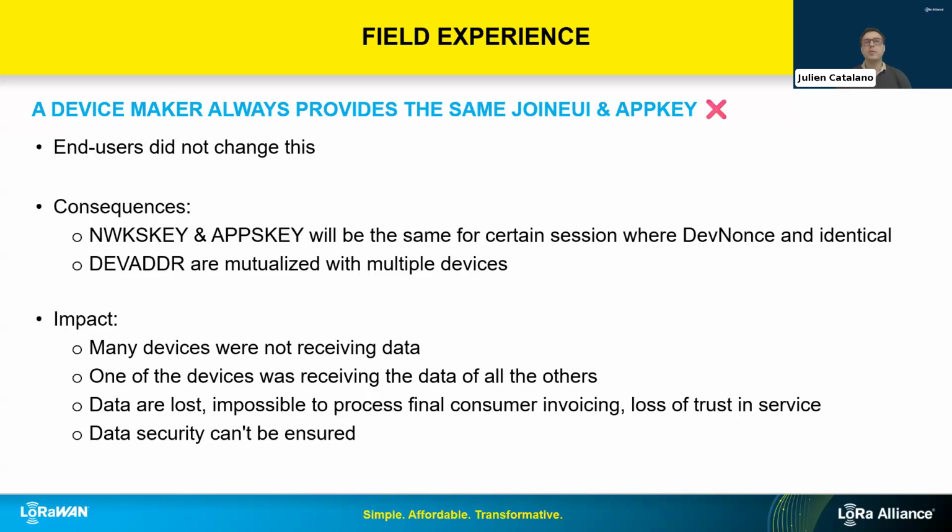And depending on your membership level, you get either a very short NetID, so a very short preamble of your device address, and the lower you go, the larger that prefix is. It's a prefix of the address, and from that prefix, it's very useful for roaming. You get the network identifier the device is hosted on.